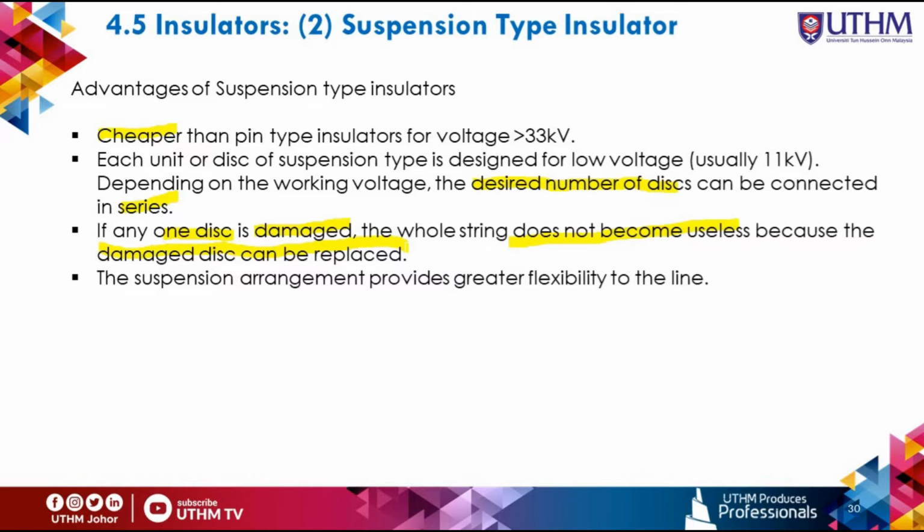suspension insulators. The suspension arrangement also provides greater flexibility to the line. The connection at the cross arm is such that the insulator string is free to swing in any direction and can take up the position where mechanical stresses are minimum.